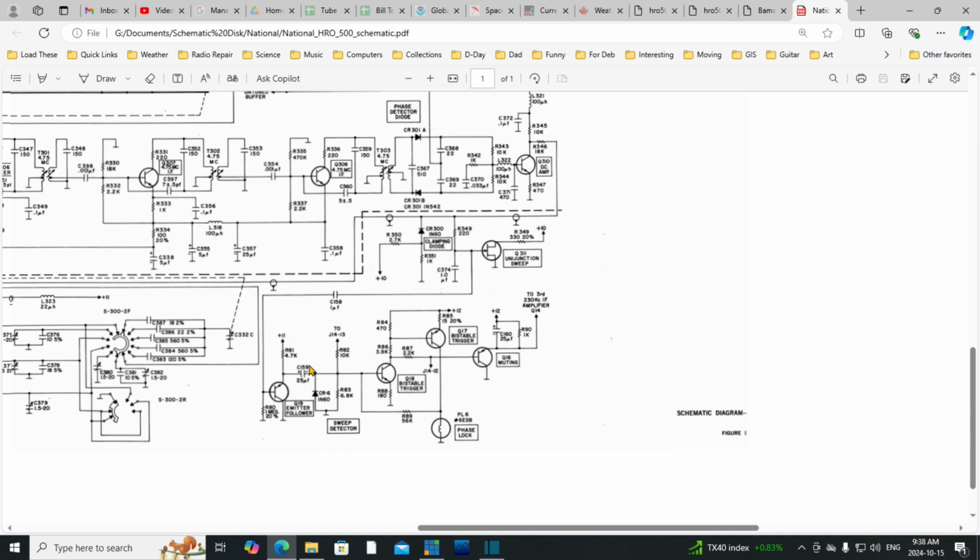So if either of these are acting up, maybe that would cause a disruption in the operation of the circuit. The fact is, this light operates exactly as you would want. It looks like that whole circuit that synthesizes the frequency is all working right. So you could conclude that if this is working right, this is working right, this is working right, everything's working right, what's left out? This guy's left out, this capacitor's left out, this resistor's left out, and Q14 itself, and other potential problems.